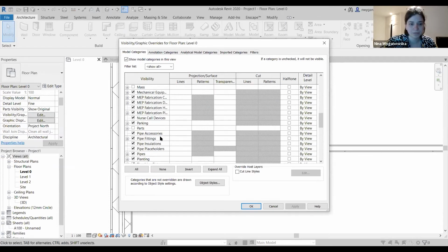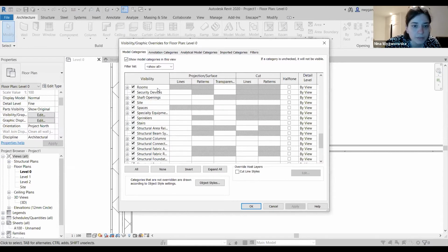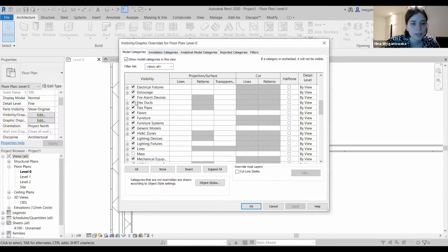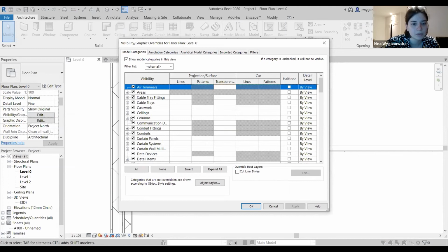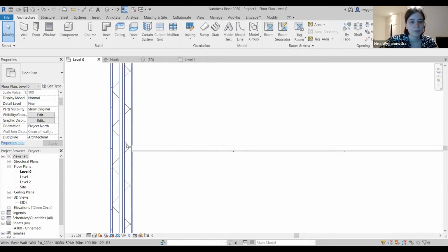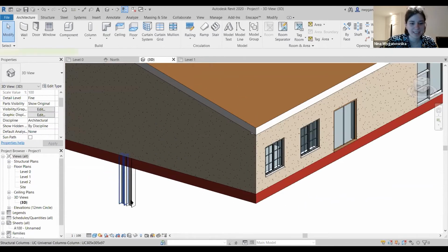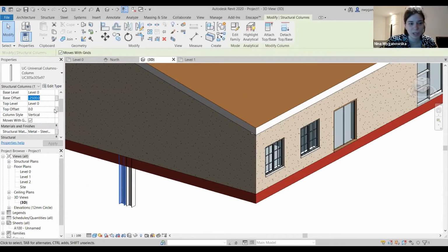project right now. So I should have columns visible. I don't know why it's not, but it should be visible. If I apply it, I don't know why it's not visible. Sorry, see, oh, because I made a mistake and set it up basically from minus whatever to top constraint. So that's why it wasn't visible in mine. It probably should be visible in yours.